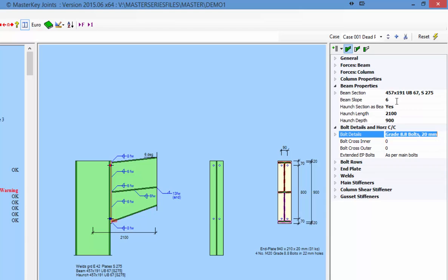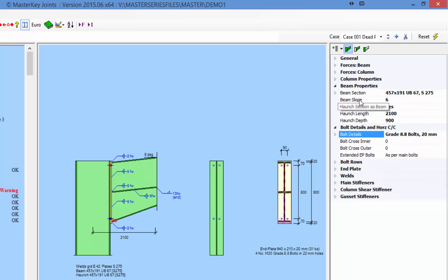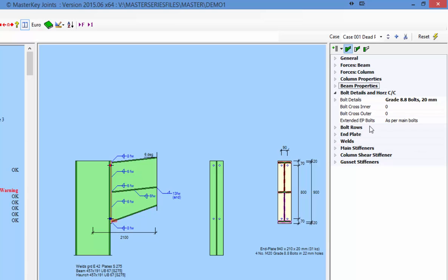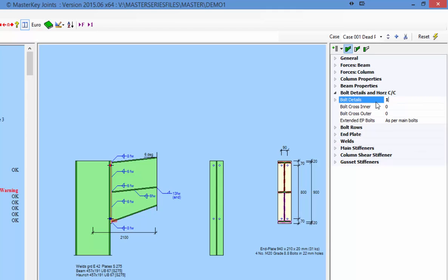Okay, bolts, grade 8.8. If I wanted to change those, I can click inside and expand that and come in here and then choose the value. But I don't even have to, because if I come back to my bolts, I can just come in here, sorry, and just type in 10.9, and it will know that that refers to the bolts, not their diameter.